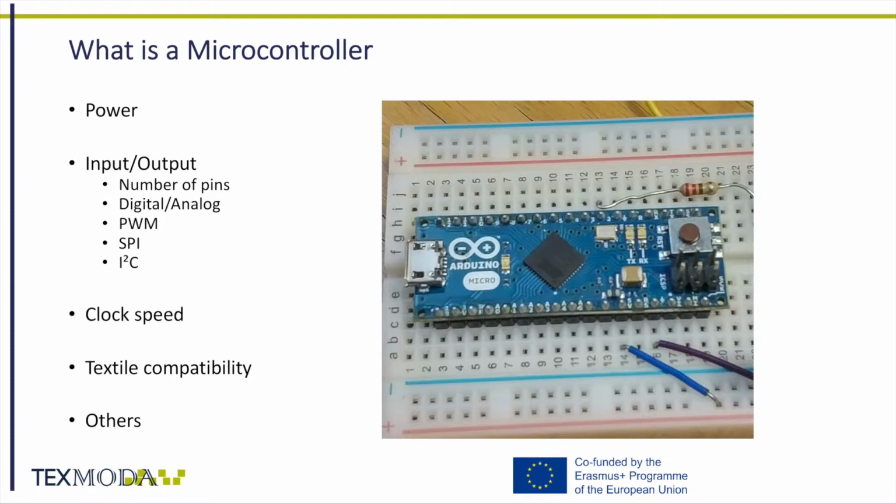First of all, the power source is important for a microcontroller. The range of operating voltage decides the choice of power source. The possibility of regulated power supply by the microcontroller is important as well. That decides what kind of sensors or actuators can be connected to the microcontroller.